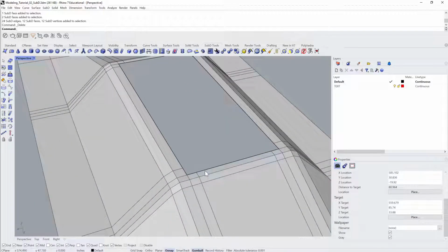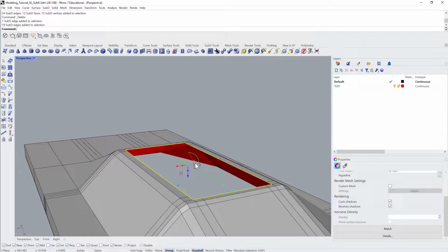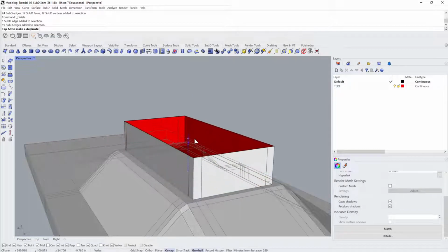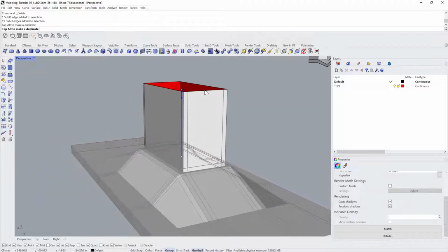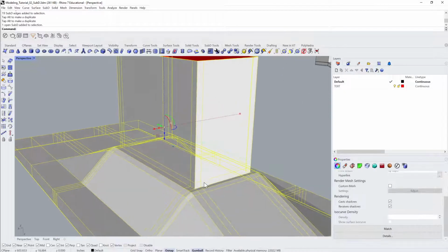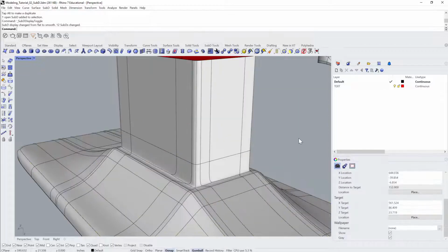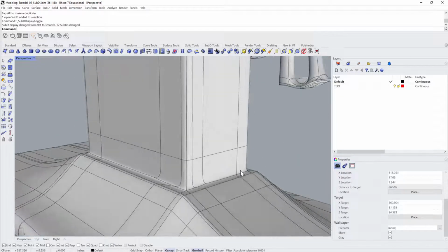And then, that's being understood as an edge loop. And so rather than going through the time-consuming process of trying to stitch everything, I can just delete what's not working. And then if I just extrude that out from that edge, now I can see that everything's lining up.